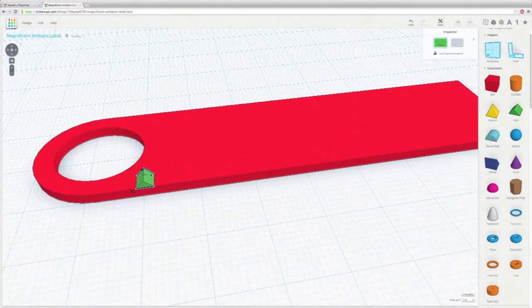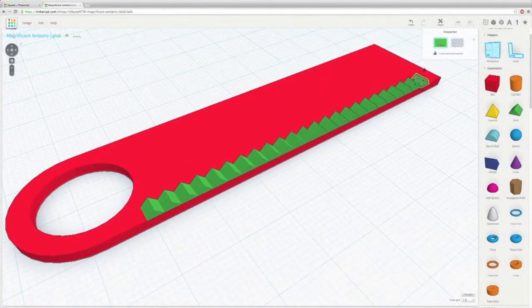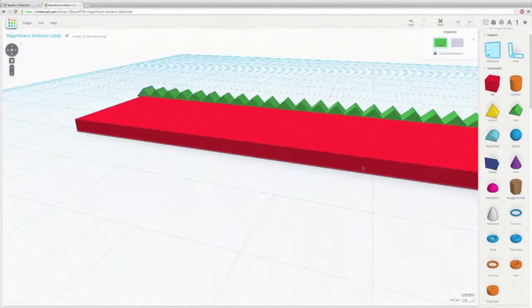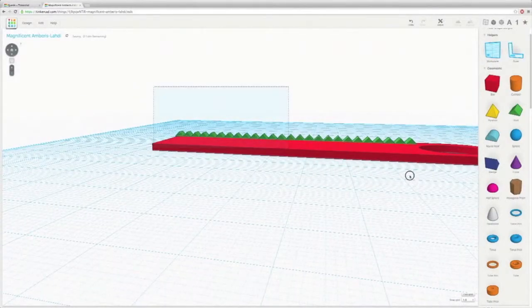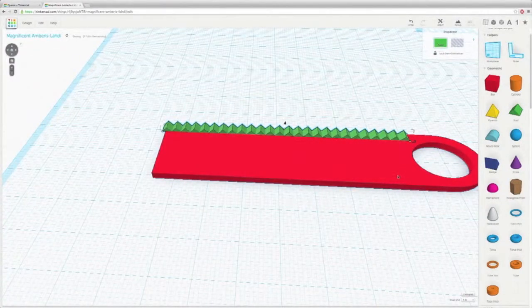And now I'm going to hit Command D, or Control D on Windows, to duplicate the object. It glowed yellow for a second to let me know that. Alright, and if I move it and continuously press Command D, it will apply the same transformation of the last copy. So I've moved it, and I'm just going down the line. One more. Okay, I got it. Alright, so here's another thing to save time. I'm going to select all of these, and I'm going to deselect that by holding Shift, and I'm going to group them together.